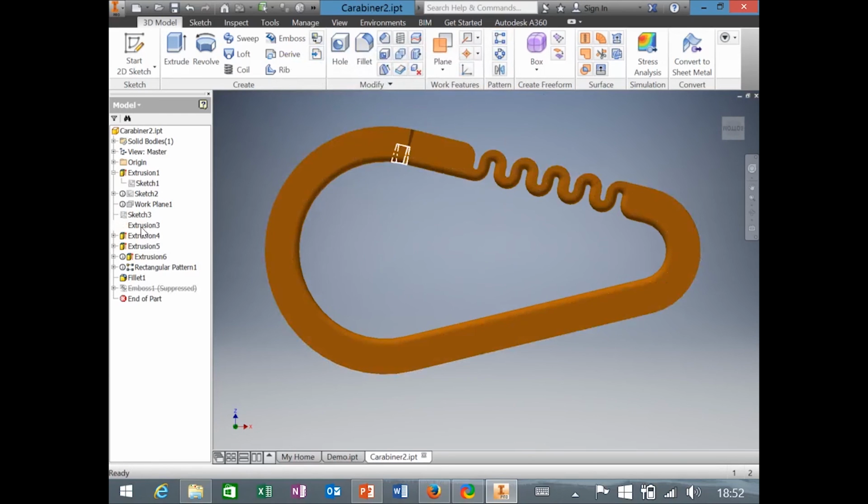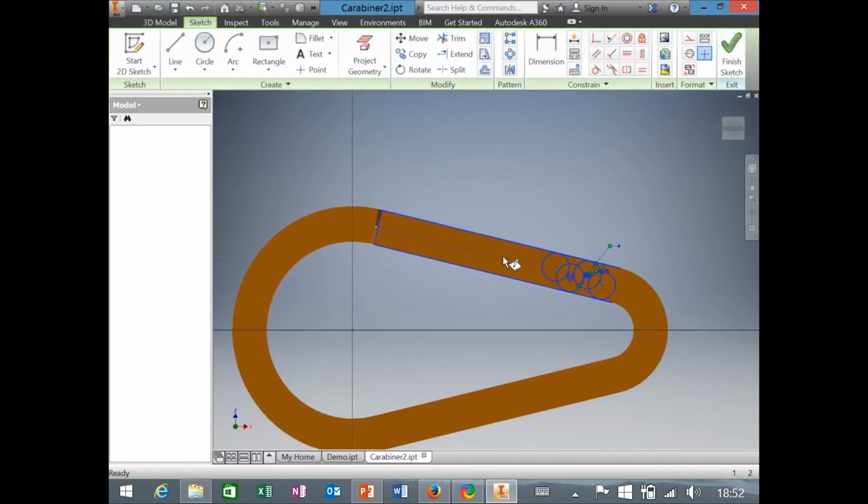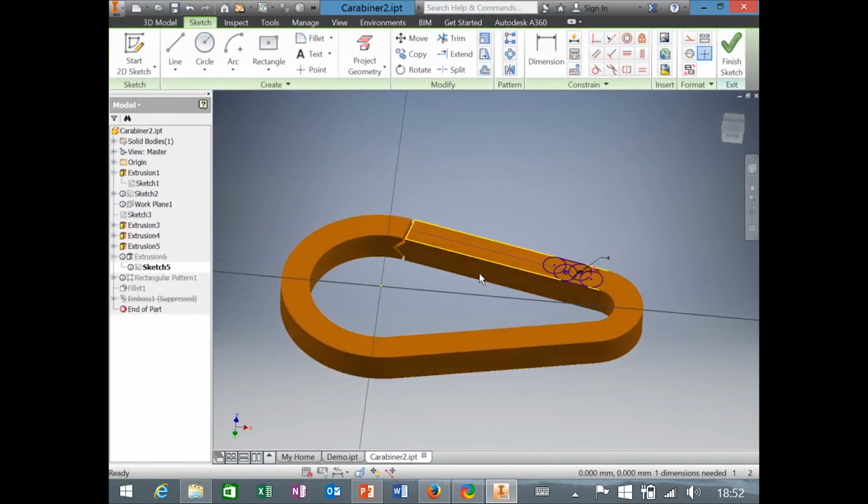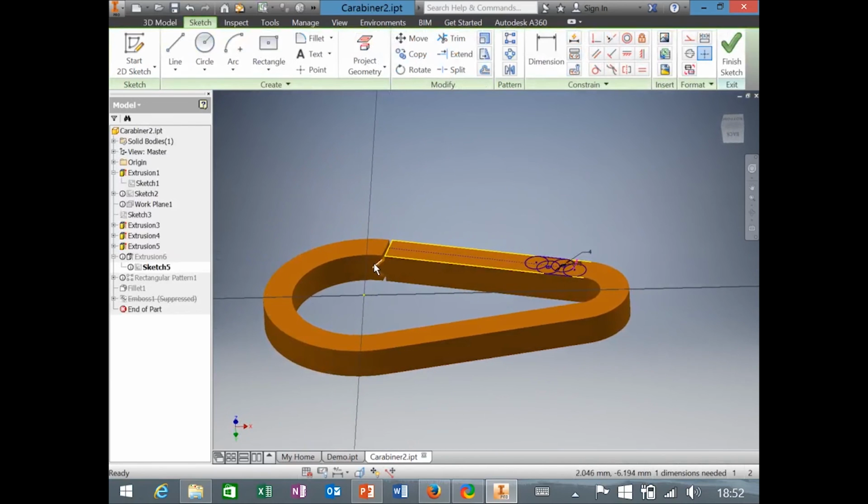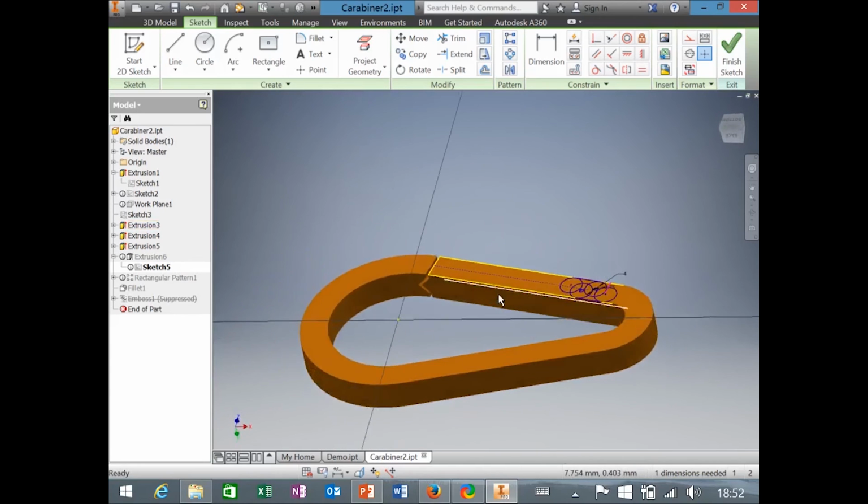So we'll look at how that looks. So we can scroll through the hierarchy, and it'll highlight stuff as we go. This is the one that defines that shape. So we'll expand it and look at the sketch. So the sketch was defined on the face of the extrusion from before. So we had that sketch and we extruded it. And don't mind this little slot here. This was done by some other sketches. But essentially, this is the sketch that we saw the first time extruded into space along the z-axis. And that produces this little profile.